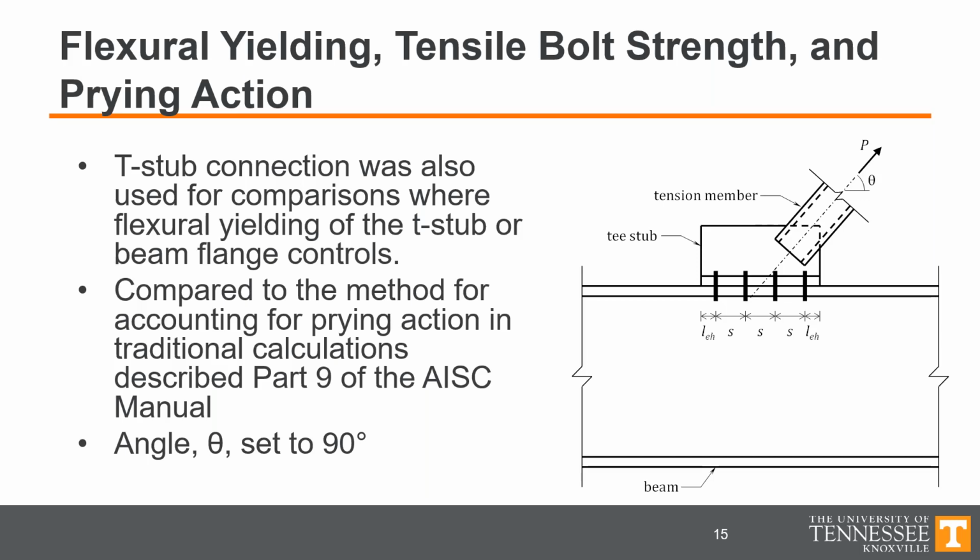There are no M equals FY S calculations going on behind the scenes in IDEA StatiCa. It's really the fact that IDEA StatiCa captures the yielding as part of the material nonlinear analysis and further applies a plastic strain limit of 5%.